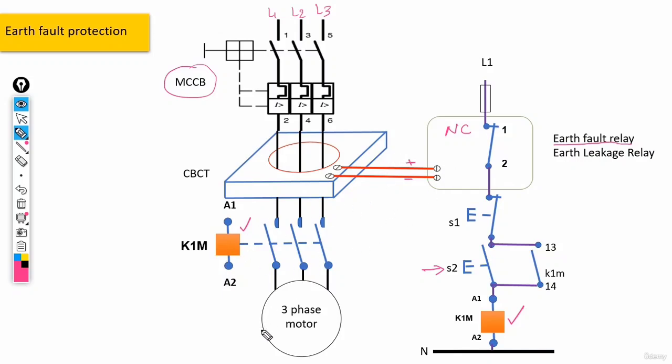Okay, now guys, once more, for any kind of reason, it doesn't matter what, if we ever got any fault current, we would get this signal here, more precisely, a positive signal here. And this positive signal causes the normal closed contact to be opened, and then the electrical current would be cut off, the contactor would stop working, and as a result of everything, the motor would be turned off. And yeah, guys, basically this would be another method that we can use for applying further earth fault protection in our three-phase motors.